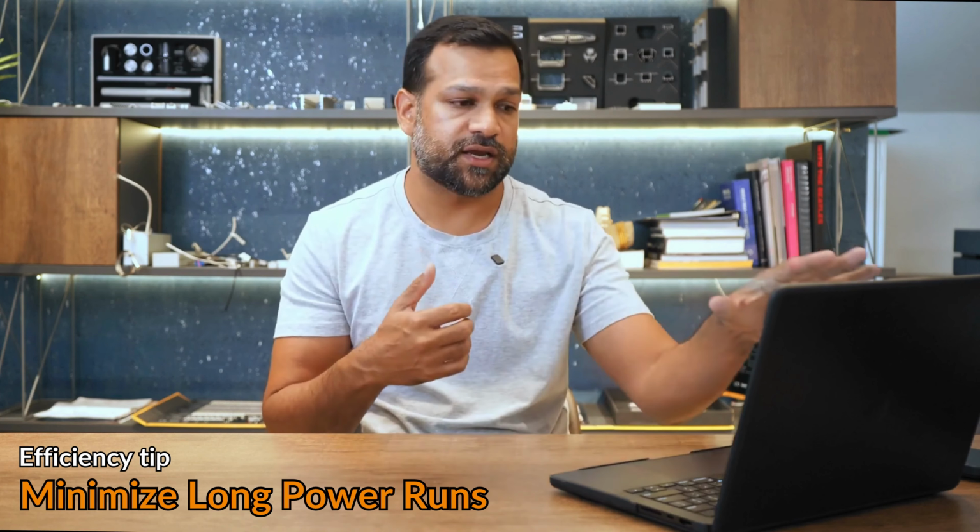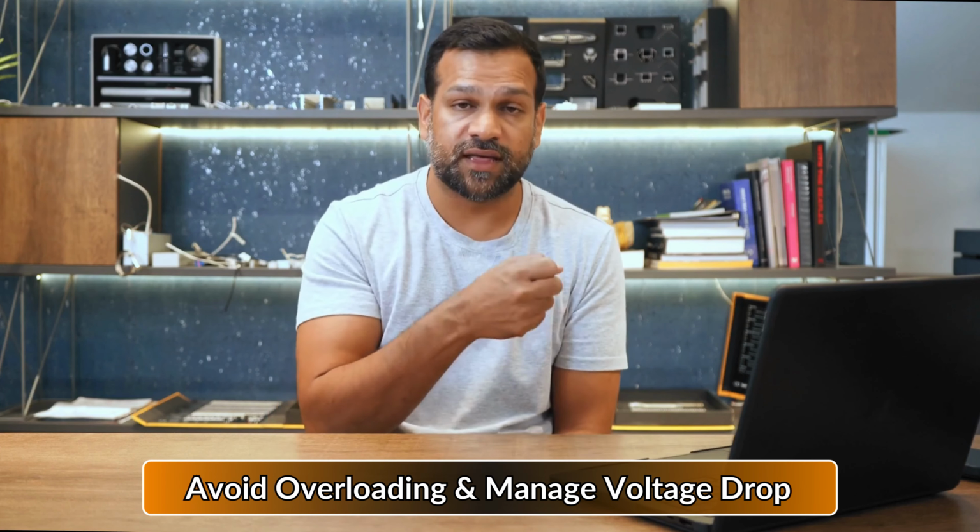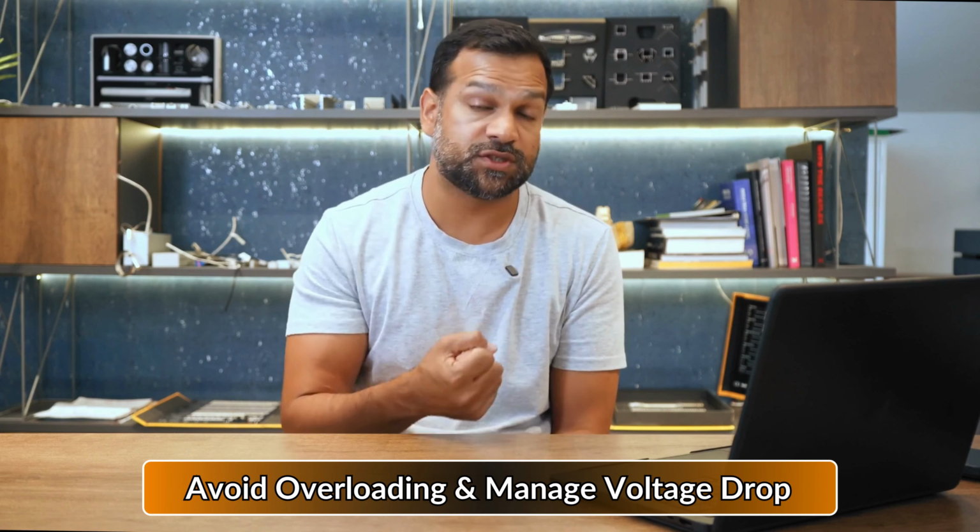So you could do it like a distribution box, where each wire from the stairs goes back to that one box and a thicker wire goes back in. You have to use your engineering here to ensure that you don't overload that wire and the rating for that wire, and you also have to manage voltage drop. And we'll address that in the E.